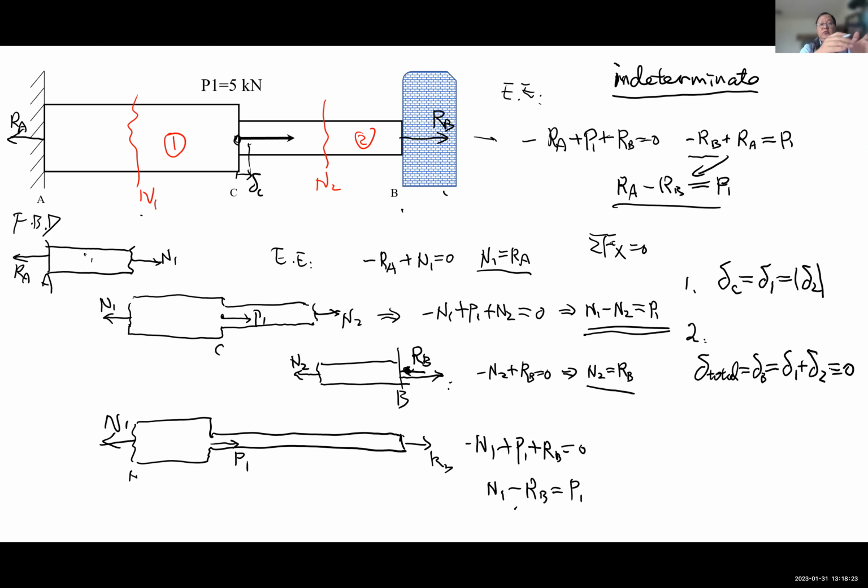If you imagine you have this load P1 applying here, and then you have the RB applying here, so this is like a non-uniform bar. You have a P1 applying in the middle and then RB applying at the end. So imagine you have the right load RB there, then the pulling and the pushing add together and make this point perfectly not move.